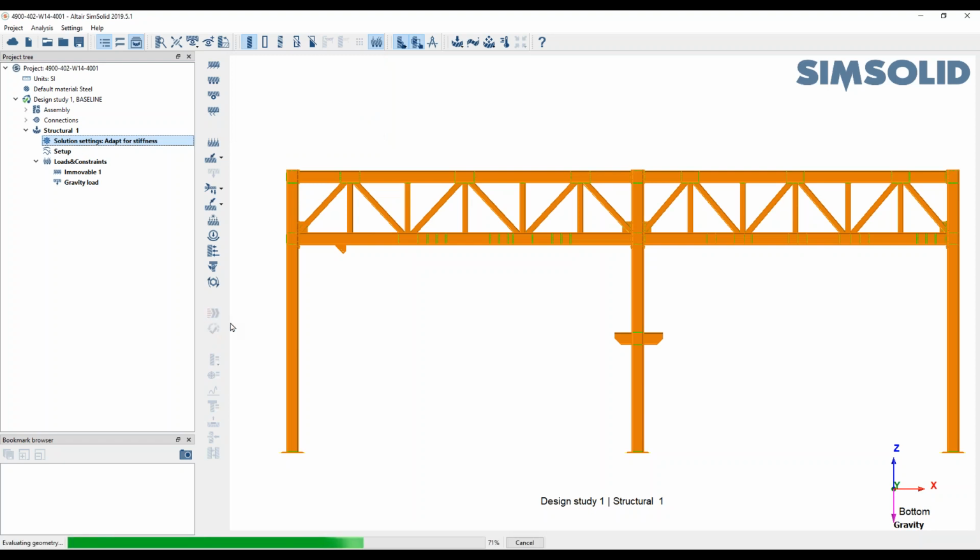And this would probably take a minute or two now. If we were to do something similar inside Nastran, perhaps as a shell model, I think it's probably going to take you more than a couple of minutes. And if it was solids, then that will take you a good half an hour to an hour, even longer, I have found, when it's with all solid elements.